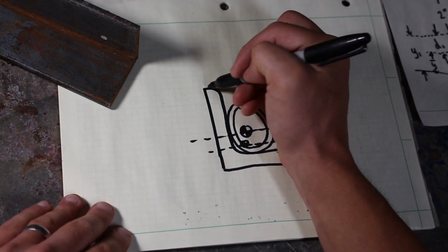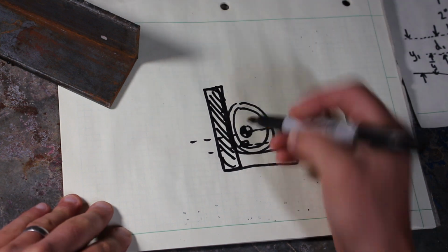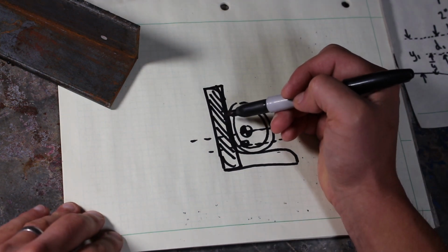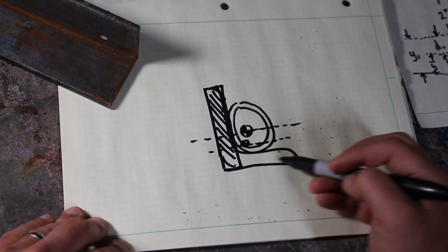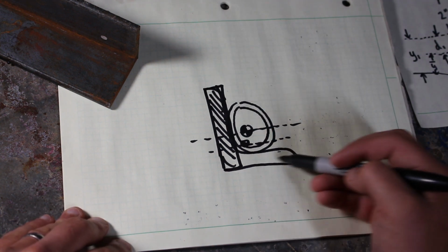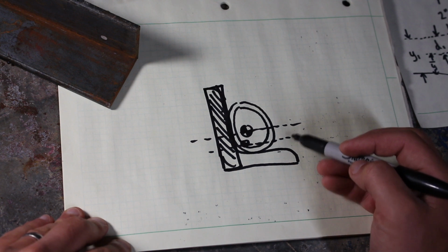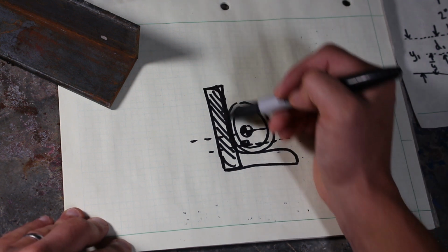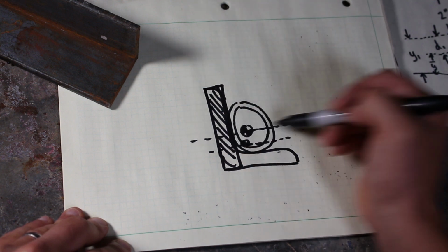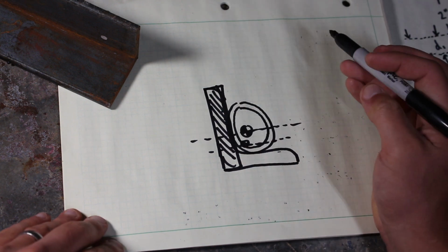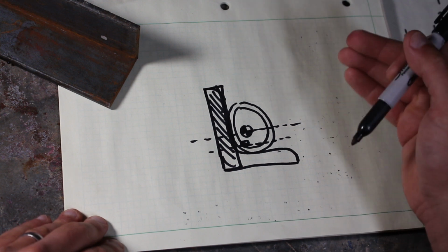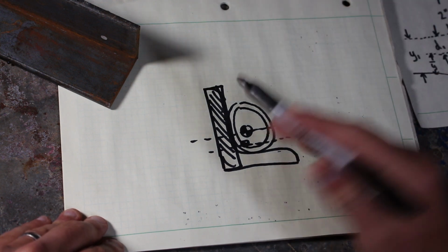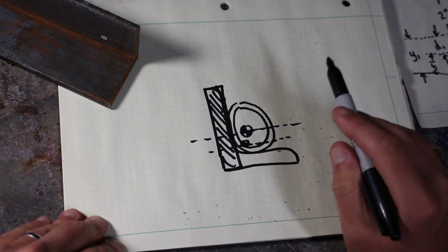In practice, I just model it as the stiffer leg and look at the angle as if it's just a piece of rectangular flat bar, because I know that this floppy component, this floppy leg that's parallel with my bending axis, is going to be contributing less to the resistance to bending than this rigid leg that's perpendicular to my bending axis. And I don't recommend shortcuts unless they're making your analysis more conservative. Shortcuts that make your analysis less conservative are cutting corners and not good.